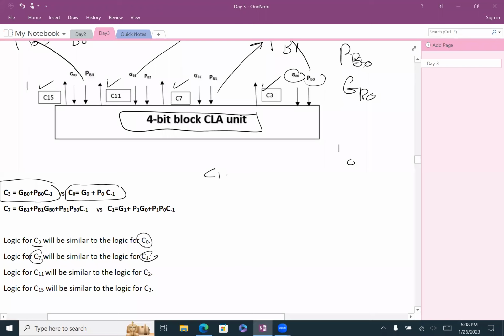Now, what's the C0? Just remind me. When will you have carry as C0? Now, I think it has become easy to remember G1. So you generate it at G1, or you generate it at level 0 and you propagate it through 1, or it's coming from outside and it's going through B0, B1. Now, can we rewrite that with the block B and G? Yes. So how can we do that?